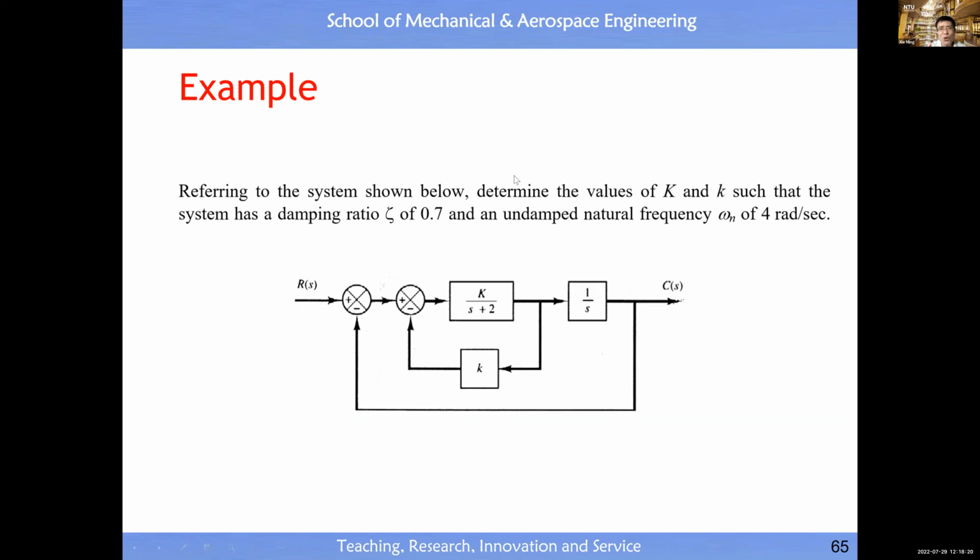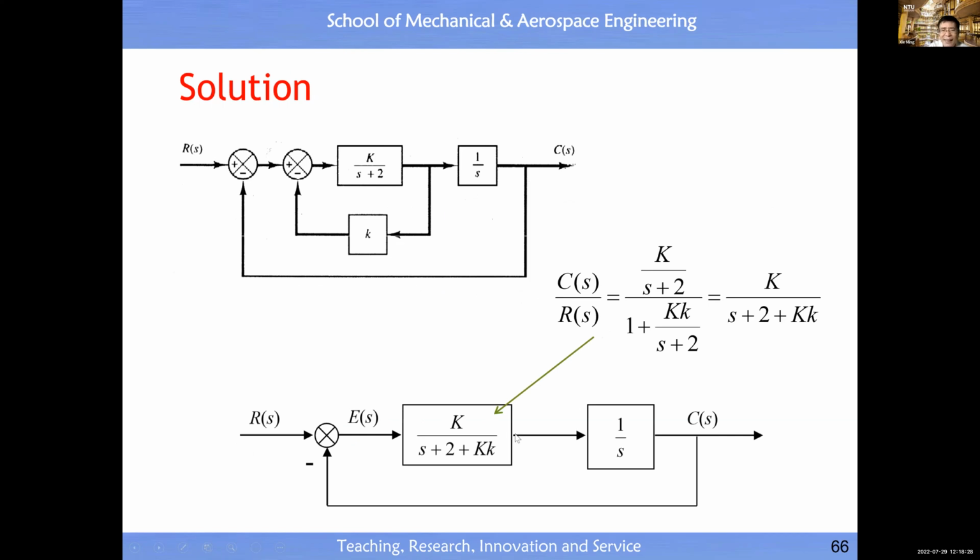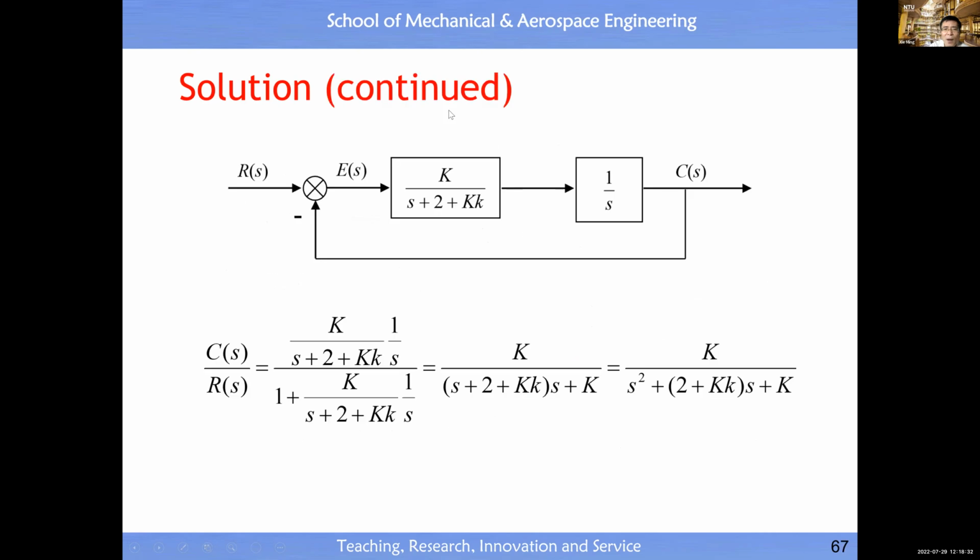This is a typical control loop of a motor, right? So inner velocity control of the motor, outer position control of the motor. Then we can write down what is the equivalent transfer function of the inner loop, then what is the equivalent transfer function of the outer loop, then it looks like this. Now immediately we want to know what should be the value for K and the small k, all right?